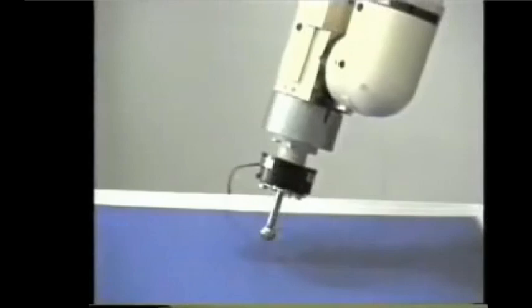What does it mean? That the robot is in fact position controlled at the Cartesian level or at the joint level. Now we imagine that this is made at the Cartesian level and the inversion is performed inside the scheme, so with the Jacobian inverse.